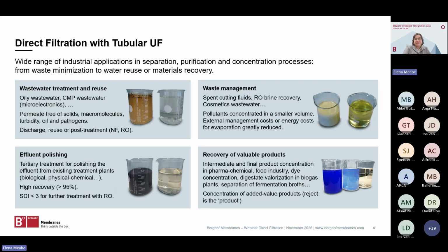So now let's explore the potential applications of direct tubular ultrafiltration. First, we have wastewater treatment and reuse. Some examples can be oily wastewater treatment or CMP wastewater from the microelectronics industry. Secondly, we have the waste management group, meaning that tubular ultrafiltration is used for reducing the volume of waste to be managed externally, or, for example, when evaporation is applied, the energy costs are greatly reduced.